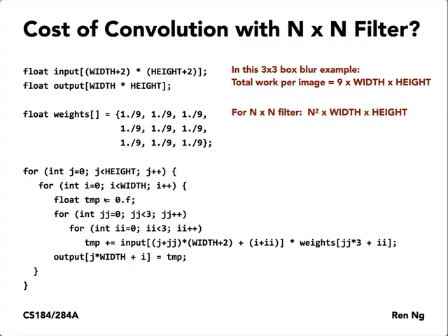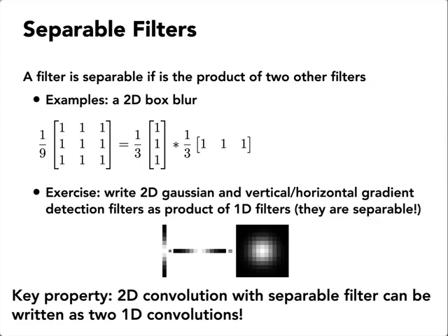So the ASIC engineers that were responsible for implementing that would really debate what size denoising filter they could afford. Is it 13 by 13, 11 by 11, 9 by 9? So these were the ways that those trade-offs played out in that case, okay?